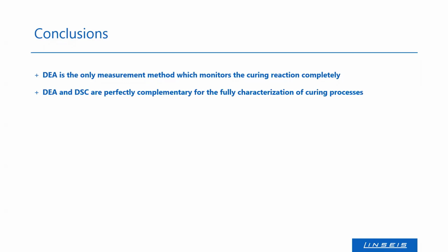DEA and DSC match perfectly to give you complete information about the curing process itself and about the analysis of the cured material to see the degree of cure, post-curing, and the glass transition.